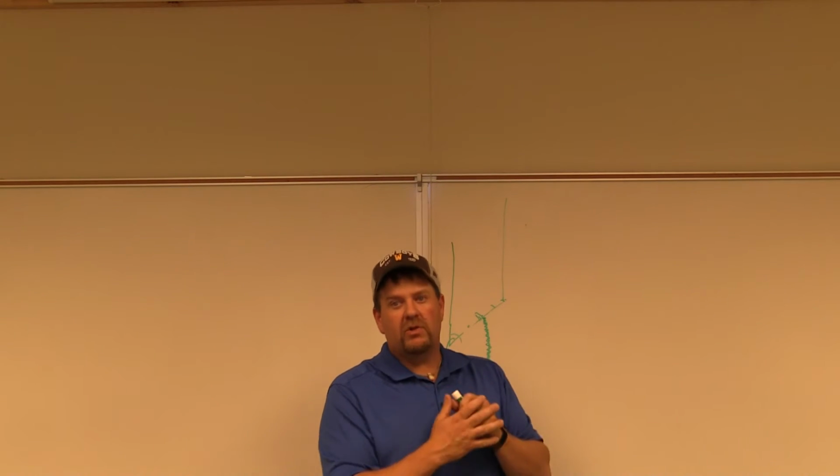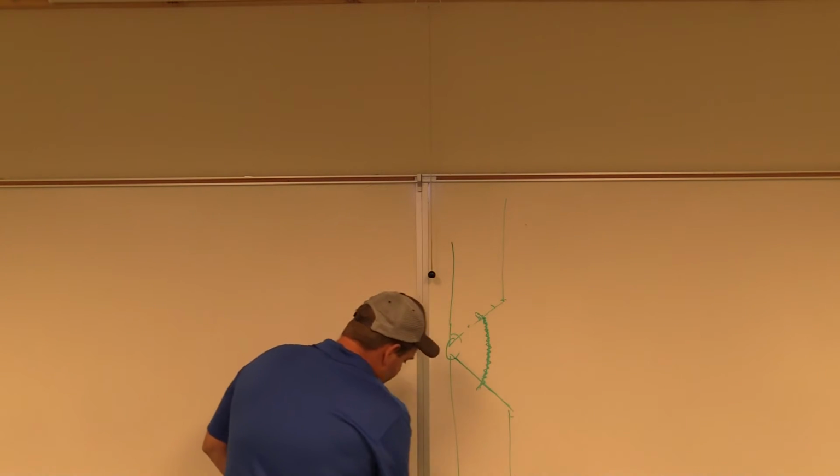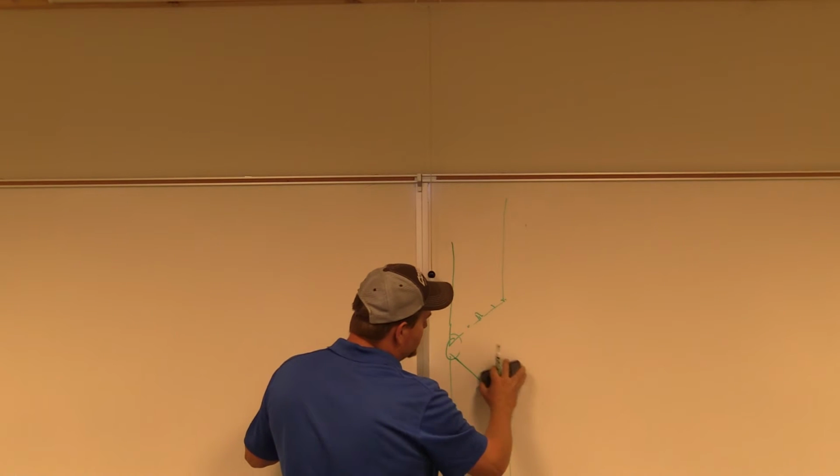I want you to take a grinder and just skim the top surface, and you'll see the two different colors, shades of gray to a white metal. It goes down almost to a pure white metal, okay? That's what we want to get down to every time, especially when we are layering multi-pass welds,